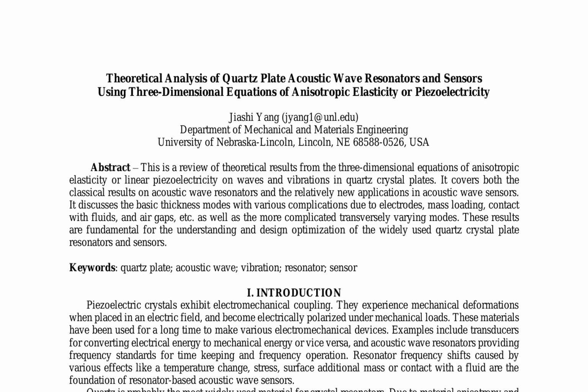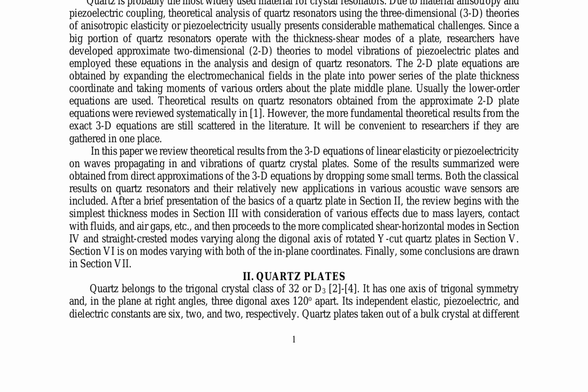The paper then delves into the simplest thickness modes, considering various complications such as mass layers, contact with fluids, and air gaps. It also explores more complex transversely varying modes, including shear horizontal modes and straight-crested modes varying along the diagonal axis of rotated Y-cut quartz plates. The paper concludes with a summary of the key findings and implications for the design and optimization of quartz crystal